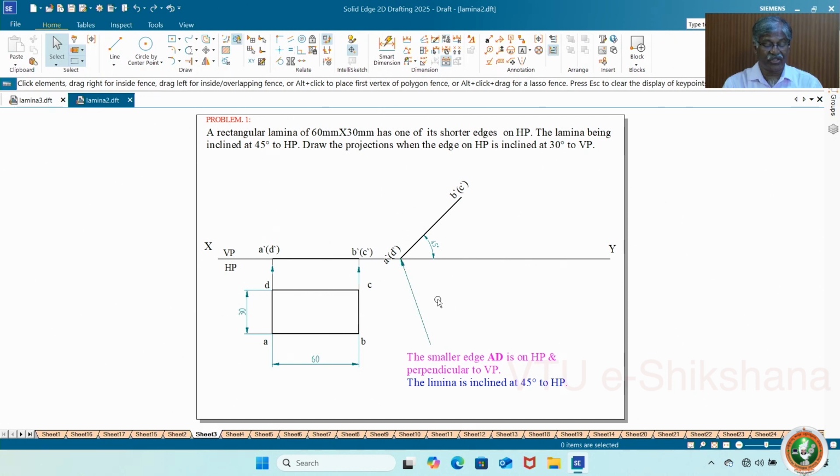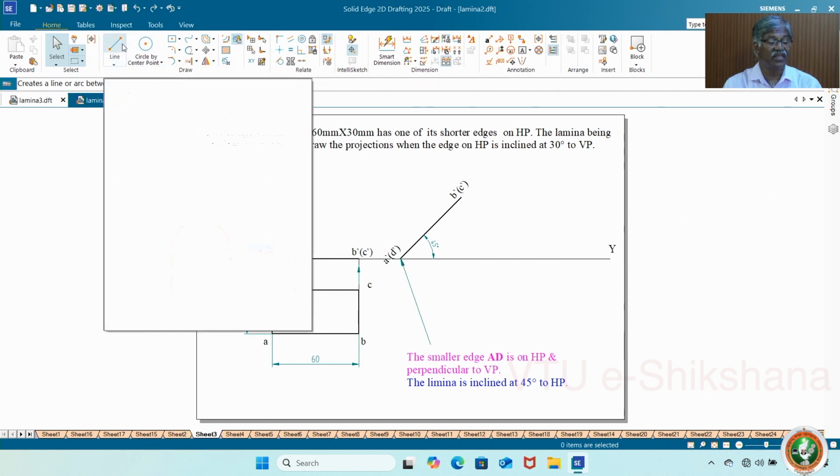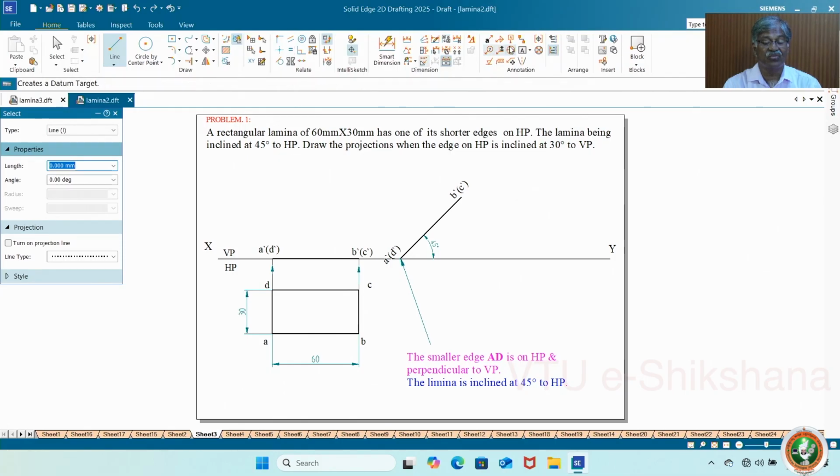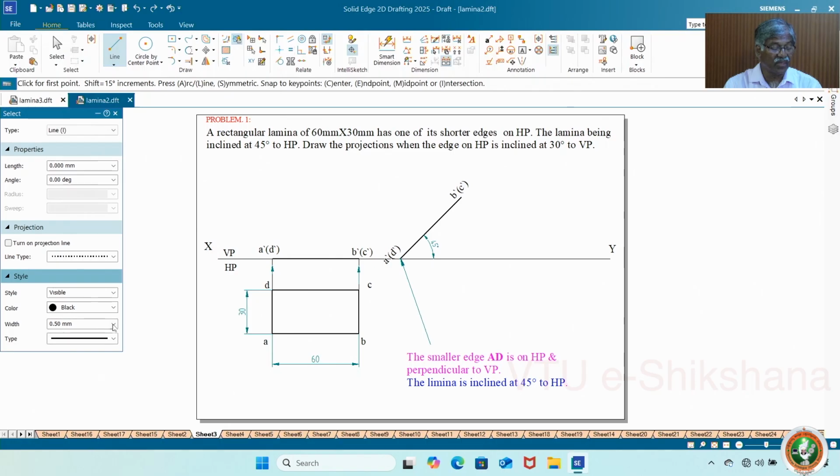Now, the projection, how to do the projection. See, here you should not draw unnecessary lines. So keep only the required lines, that is, construction lines. You first fix the right extreme line and the bottommost line. With the alignment indicator you can do it easily. See, that's what. Don't cross this line. Any number of projections, it can be 10 or 15 or only 2 corners. You project only up to this from the front view to the top view, and then from the front view you do this. That's all. Here the minimum is there.